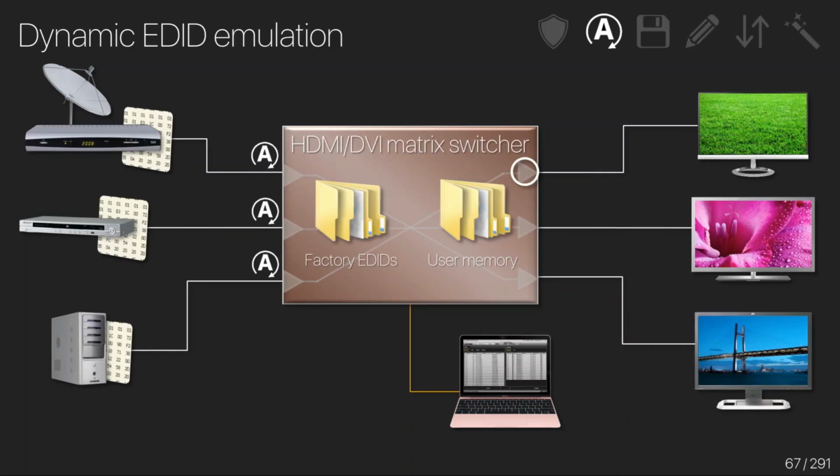If you wanted to use the EDID of that particular display, you could always just save it into the user memory and then emulate it from there statically. However, there is a situation where dynamic EDID emulation can help quite a lot.